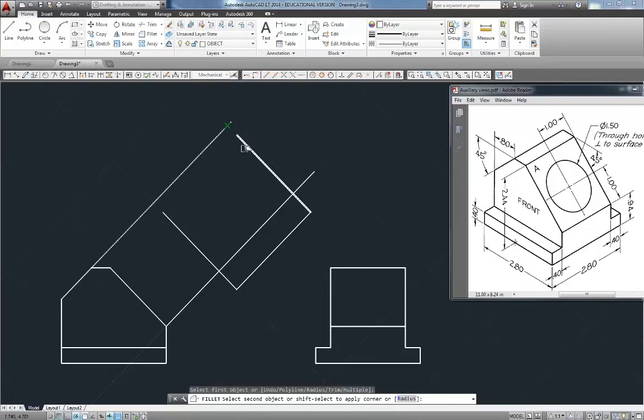You don't really have to do this when you work with auxiliary views. I just want to get a box here. And I know that box is going to contain the view that I'm after. I don't know what it looks like yet, but I know that box is going to contain the view. All right, I have this corner projected. It's right here. And that separates this vertical surface from this angled surface. So let's deal with this vertical surface for a minute here.